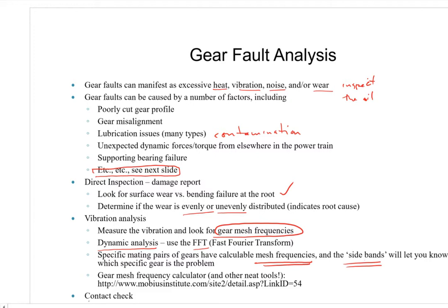And I knew it was improperly cut because I asked them to do a contact check, which is the last thing here on the gear fault analysis, where you put layout blue on the gears. You drain out all the oil, clean it all up, put layout blue on the mating gear sets, and turn it by hand, and do a contact check. This is also useful.